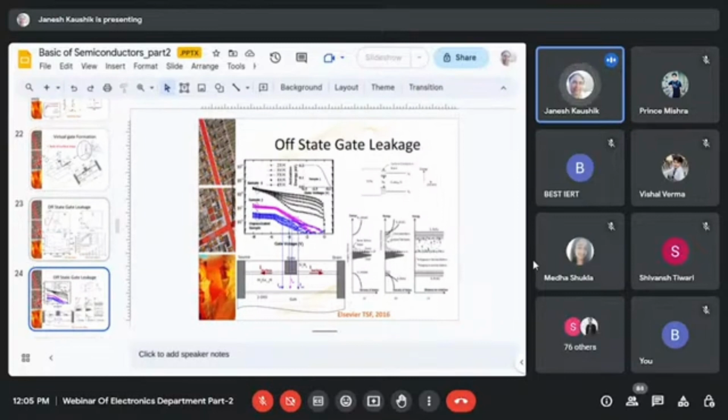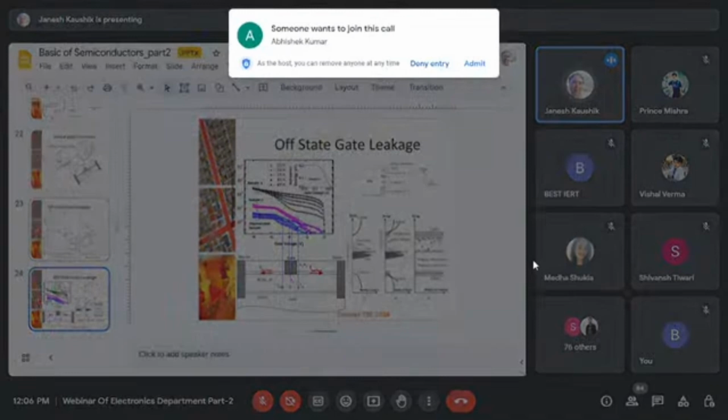That is a desirable characteristic from the gate leakage point of view, but it is not so desirable because these devices have larger virtual gate lengths and higher current collapse values. Current collapse means that when we apply a certain electric field in the structure, the 2DEG channel is depleted. The moment the 2DEG channel is depleted, our drain current reduces, and that's why we can't use these unpassivated samples for transistor operation.